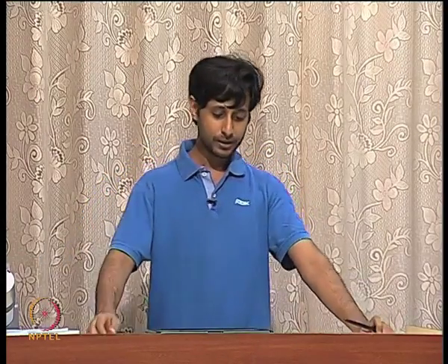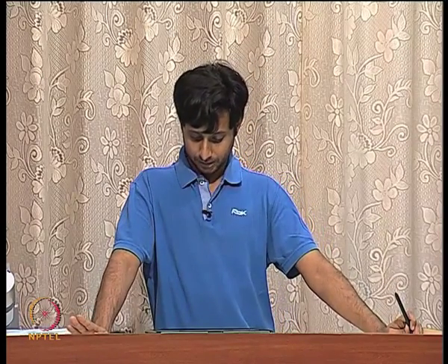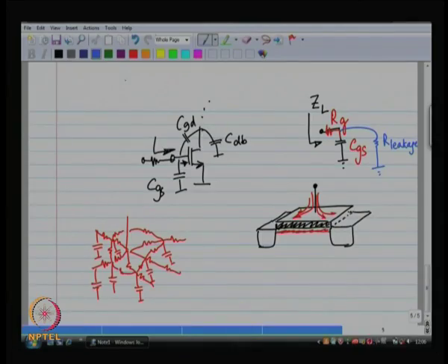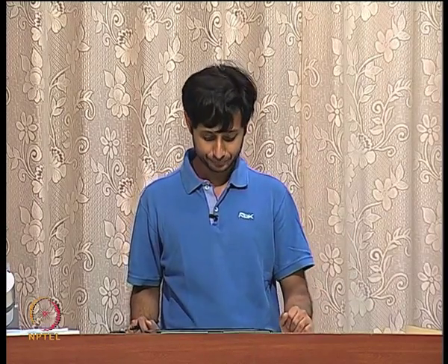Now, this is not part of our discussion, unfortunately. So, it is your homework to figure out what is going to happen when we are talking about super modern technologies. For older technologies, our situation is that we have a series gate resistance with the gate to source capacitance or whatsoever. So, this Rg is what is burning the power. So, this is where you are delivering the power.